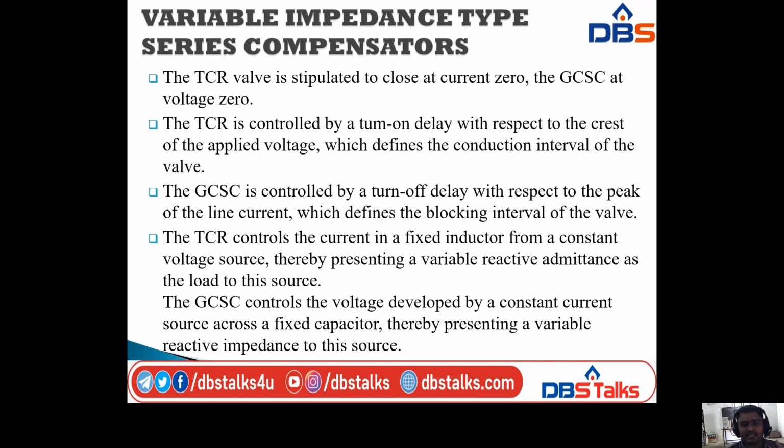Next, the TCR valve is stipulated to close at current 0 and the GCSC at voltage 0. The TCR is controlled by turn-on delay with respect to the crest of the applied voltage, which defines the conduction interval of the valve, and the GCSC is controlled by a turn-off delay with respect to the peak of the line current, which defines the blocking interval of the valve.